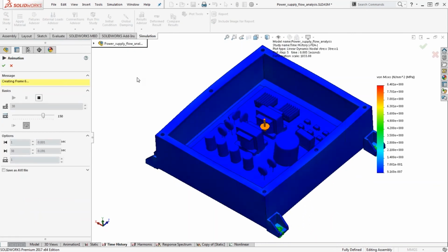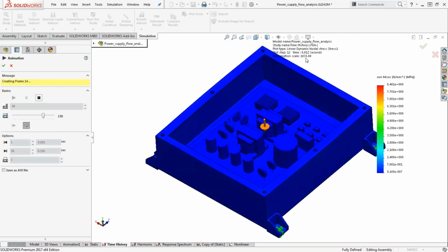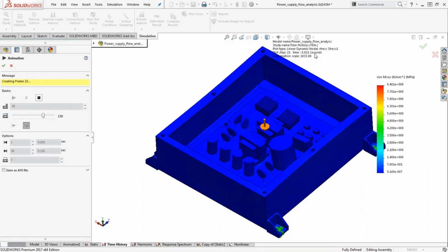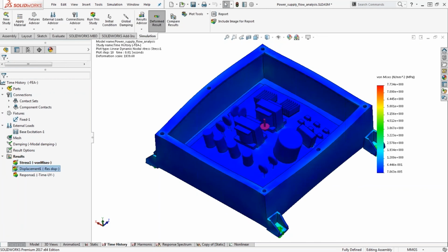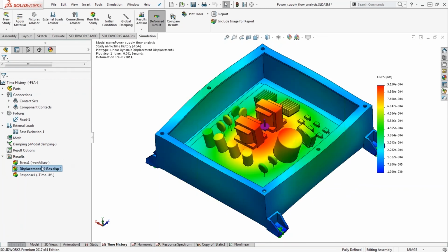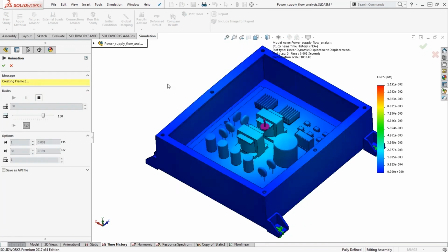you see that I'm defining a time curve where that shock is happening at 11 milliseconds. So it's happening very quickly, and I want to see how the stress behavior gets affected based on this very quick impulse shock load. So when I run the analysis, I can get my stress.